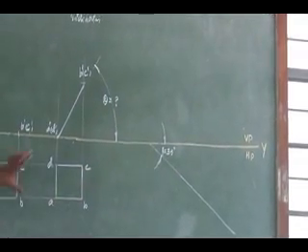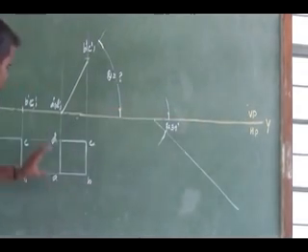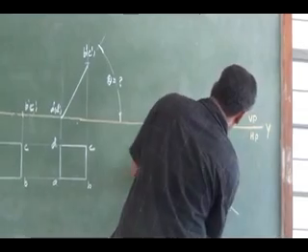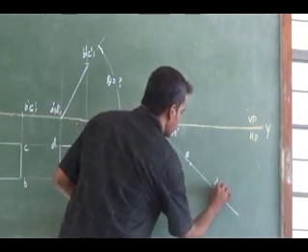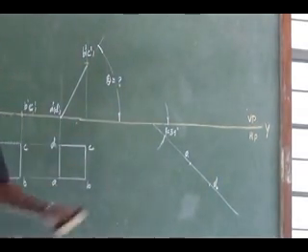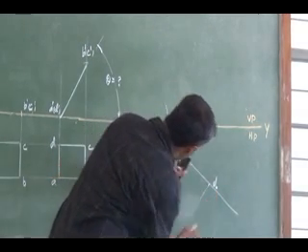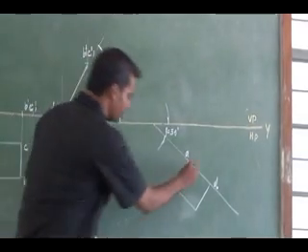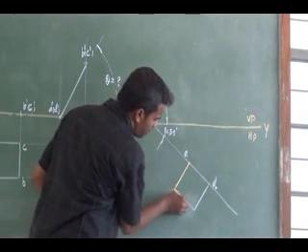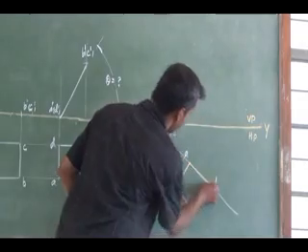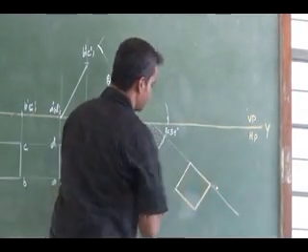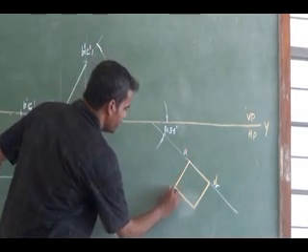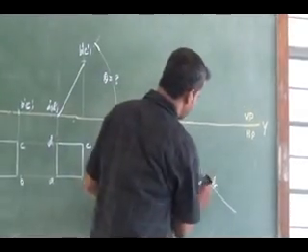On this 35 degree line, which one do I have to mark? I have to mark AD. AD is going to be my resting shorter edge, so I can measure it and mark it here conveniently, 30 mm. This is my A, this is D. Then I have to redraw the same square here, 30 by 30. So I can redraw this square. This is the final top view. As per the problem, this is going to be my final top view. I can darken this. This is AD, B, this is C.